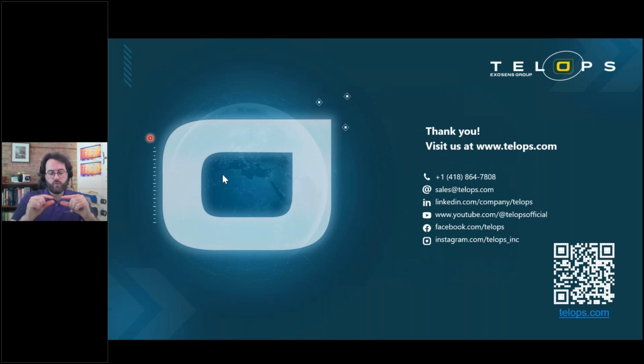materials, or each individual materials, or even your sandwich of semiconductors, having an understanding of the transmittance of those materials that are on top of your target, and then doing that modeling of understanding how much of that radiation will be absorbed and or transmitted towards the atmosphere and then towards the camera, then it can give you a good idea of what you can expect in terms of infrared measurement.